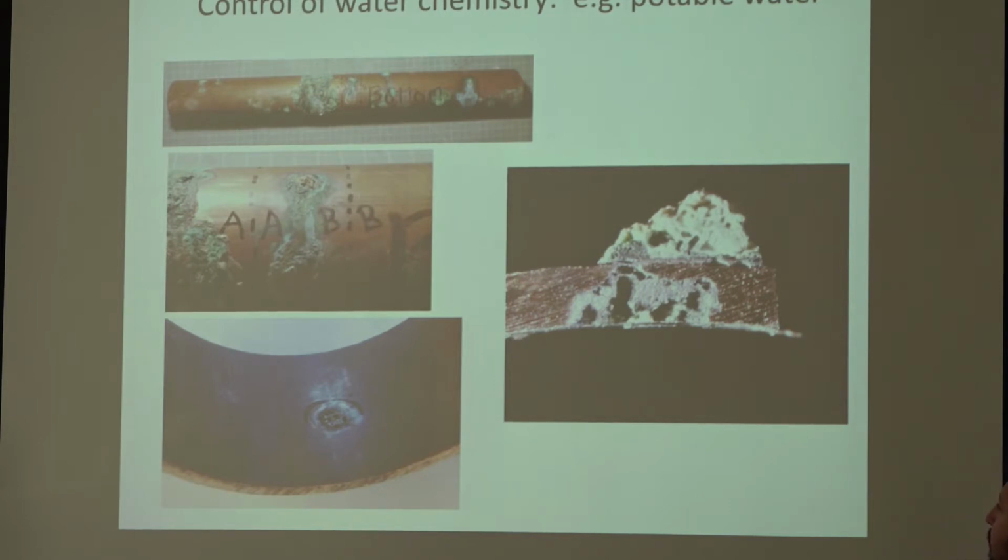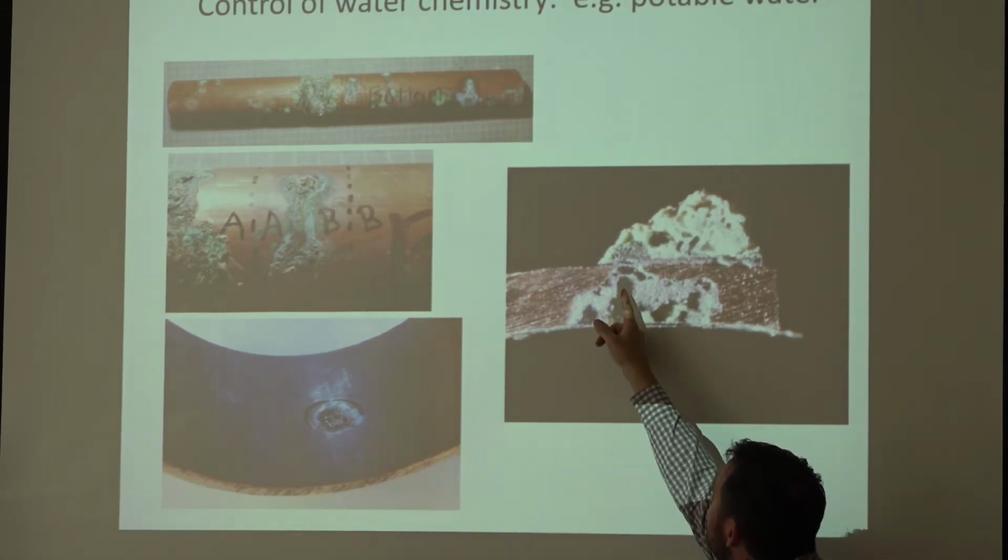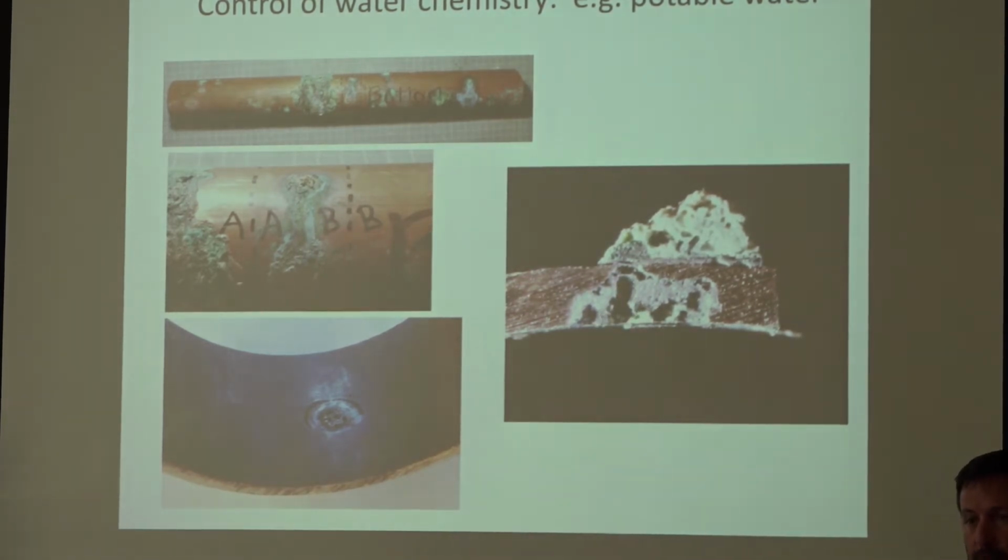But yeah, when I went to the site and started looking at it, I started really thinking, well, maybe there is an issue of corrosion here. It wasn't leaking. And the interesting thing about not leaking is that when the water from the inside was going through that pit to the external surface, you were essentially evaporating, or making a distillation of the water, and the deposits, the salts from the water, were able to clog that point. Now, is that permanent? No. It's going to form, it's going to be stable, but it's a very short-term solution.